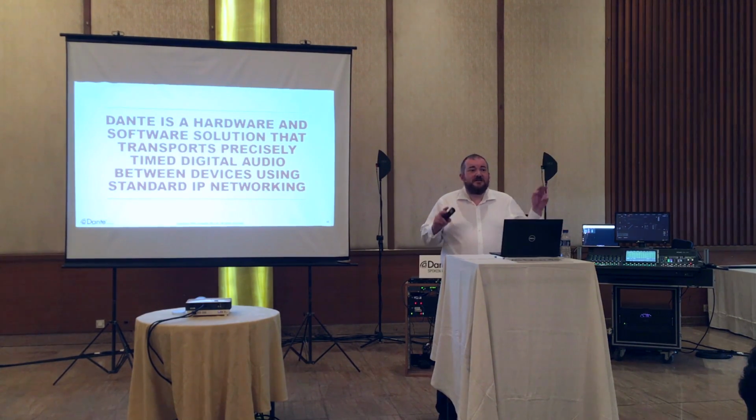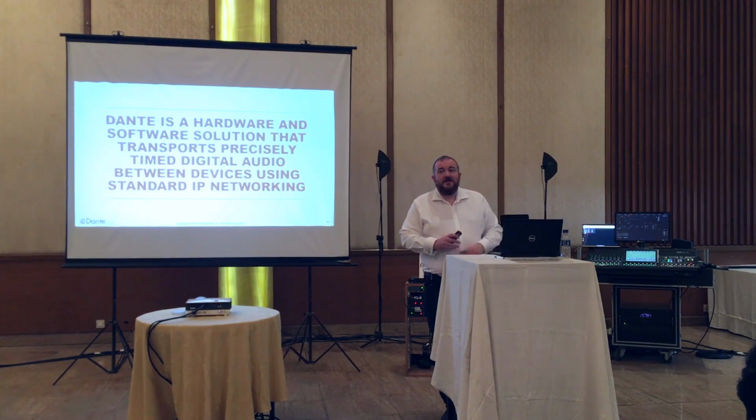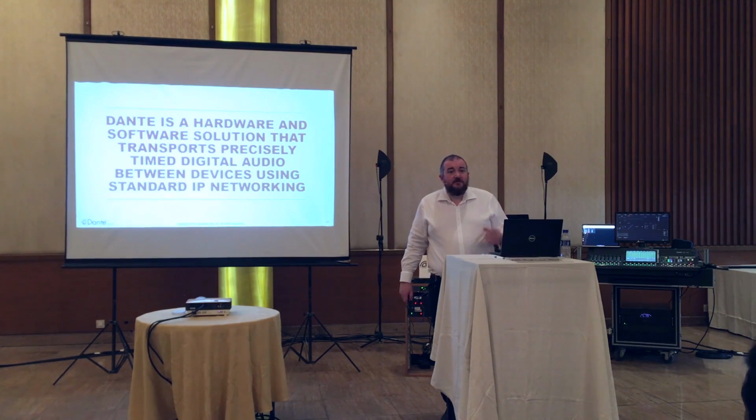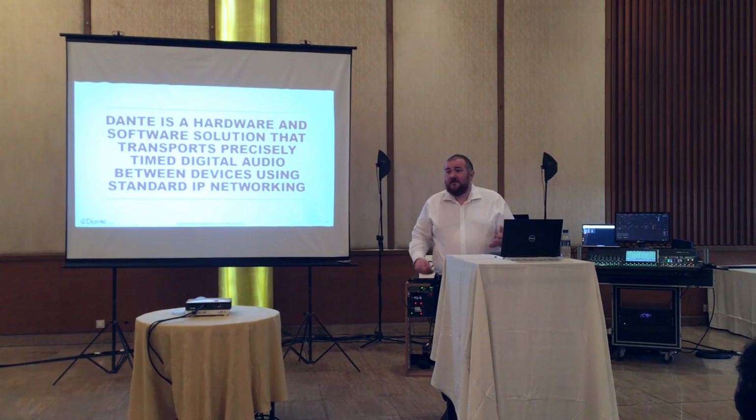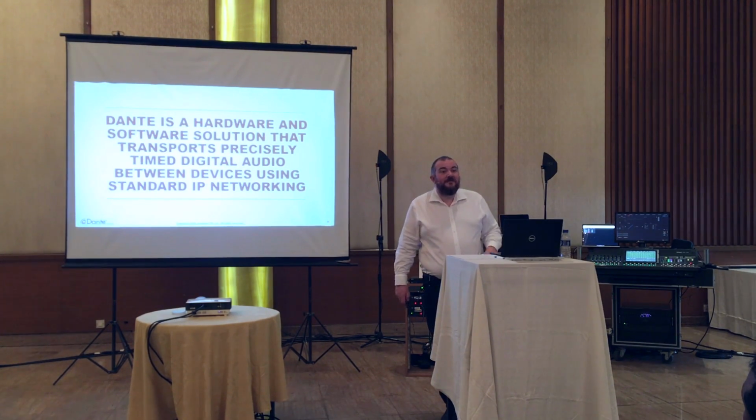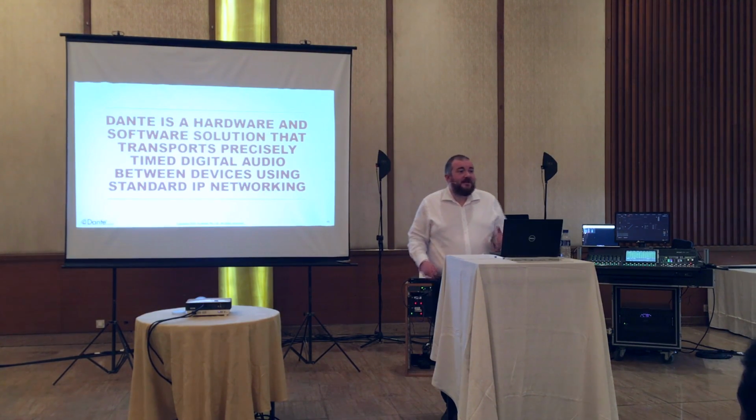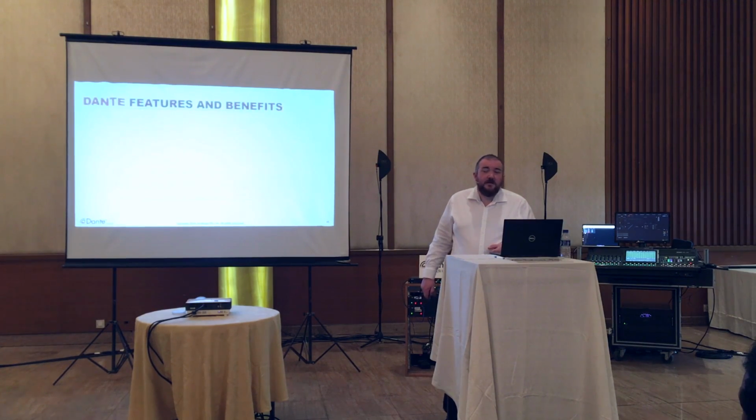We carry on doing classic Dante for those devices, and we can communicate AES67 at the same time, because that's what people want. And that means that with a new firmware version, people can put that into their devices and they can talk AES67, but it doesn't break anything behind. That's a really key thing for a technology. If we're going to be interoperable and plug into every single device, we have to try and keep that going for as long as possible. That's absolutely key to how we succeed.